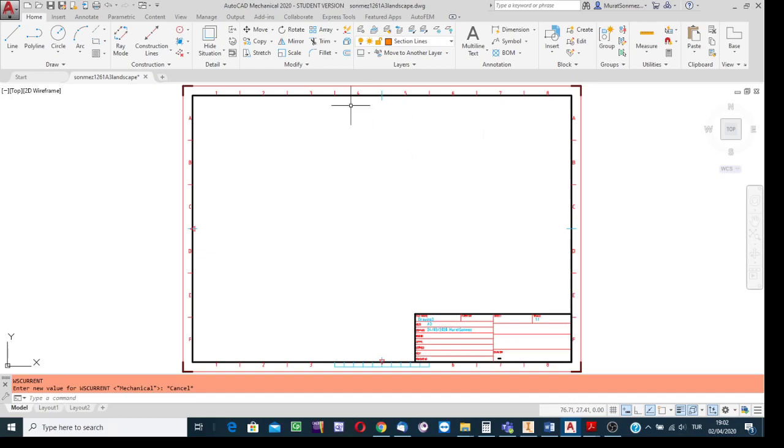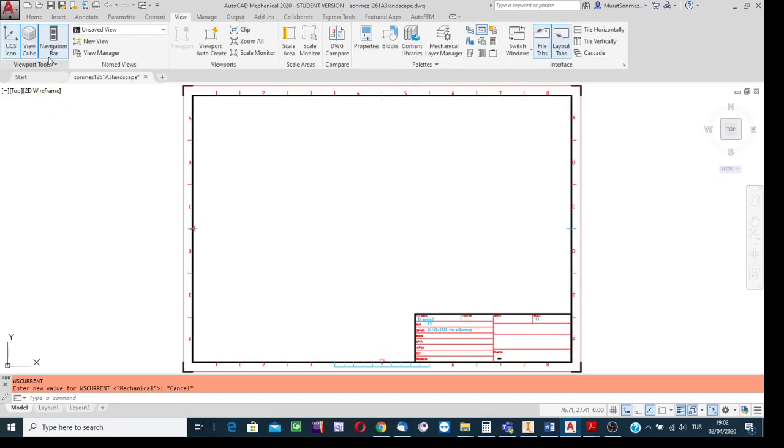Since I'm going to use AutoCAD for two-dimensional drawing purposes, you see over here at the top right corner I have the orientation cube. No need to use the orientation cube in a two-dimensional environment. So I'm going to take it away from visibility on the screen. Remind you how: select the View tab and then toggle off the View Cube button. Yes, take that unnecessary tool away.